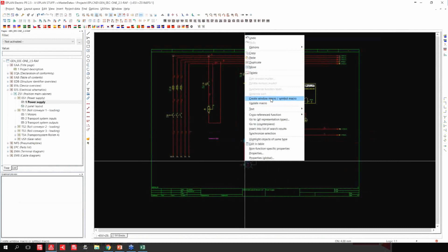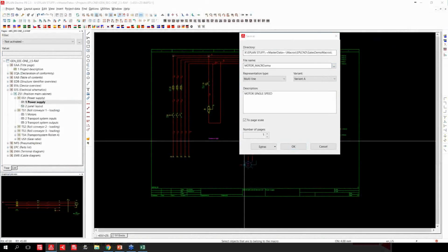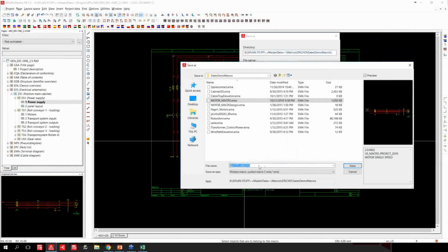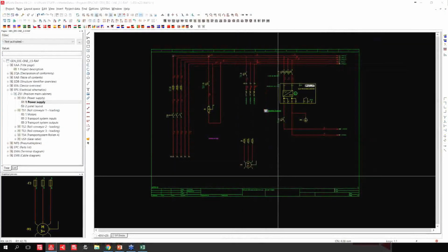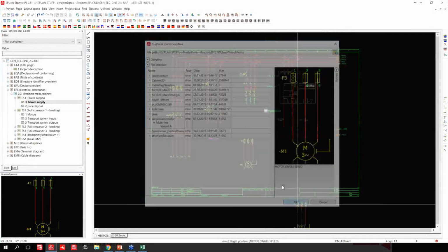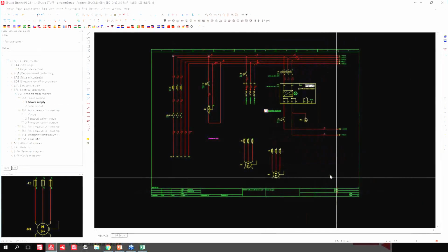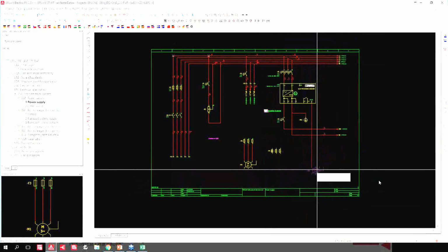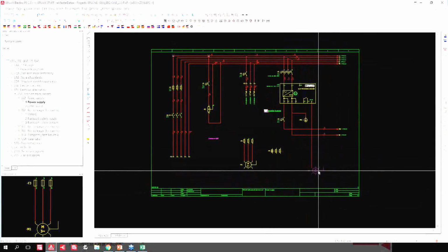here, and I'm going to say create window macro. Give my macro a name. Of course, here I'm going to call my macro Sergio macro motor, because I love my name. And once that's created, I can go back into this, insert my macro, my Sergio macro is there, hit it, and then I can go ahead and place it and use it. It's a very easy way to create macros. And of course, as we mentioned, they're all separate. They were created together, but I can always split them apart at any point in time.